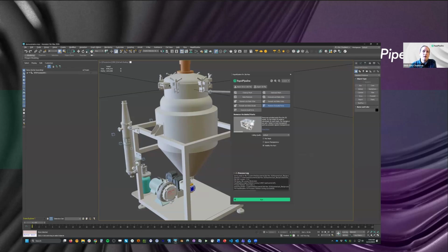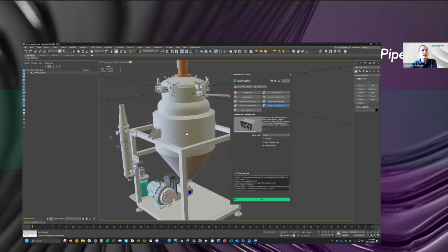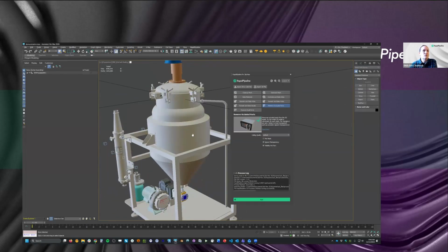So for example, this microwave has a clear window on the front that you can see, and there's a slice of pizza in there on a plate. And the culling is smart about surfaces that have transparency. It won't cull things that are hidden, that are inside the object, but are behind glass. You can tell it to ignore that. Hey, if I don't care about the pizza and I just remove all the interior parts, then that's what that'll do. Now, I don't think this guy has any transparency.